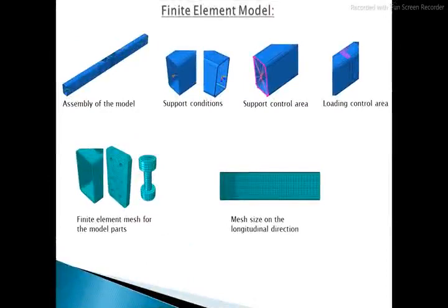Going further, a finite element model was defined to observe the response of the joint and for parametric investigations. The analysis was performed using Abaqus software. 3D solid elements were defined as part of the assembly for the RHS profile, connection end plate, and bolt, respectively. The material properties were considered from the tensile test performed on a specimen extracted from the RHS profile and from the bolts material. A pin and a roller support were defined at the assembly ends, while a displacement of 30 mm was defined using reference points in the point loading position. The connection end plate was connected to the RHS profile using the tie constraint.